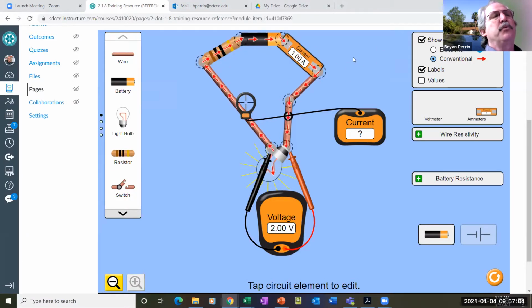Okay, and I'm going to flow through the meter. The issue with that is I'm limited to normally about 10 amps. What I'm using here is an inductive clamp. Since the electrons going through here create an electromagnetic field, an inductive clamp on a meter is able to measure that and give me a number without breaking into the circuit. So with few exceptions, we really do not put an amp meter in series with the circuit anymore. We normally use an inductive clamp unless we're looking for very, very small numbers.